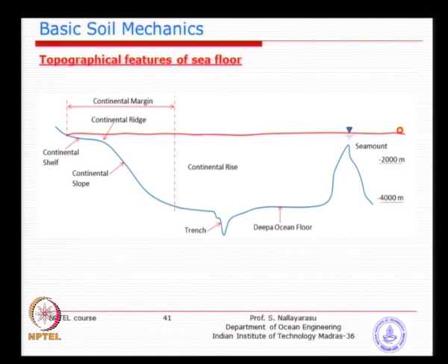You need to understand that when you are doing a structure, for example a pipeline, you cannot assume the soil layer will exactly follow the profile of the seabed, and that is why you do a borehole. When you come closer to the beach area, you do boreholes closer together, because sometimes you will not have a specific soil profile. A typical problem area is this one, where sometimes you will not even have that particular layer.